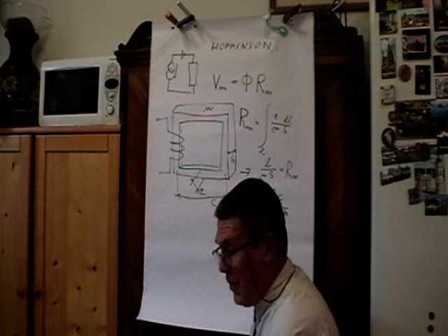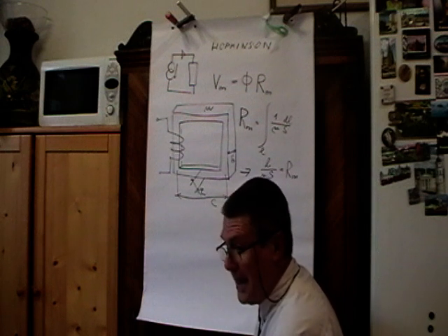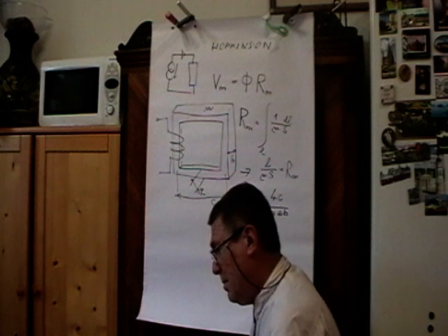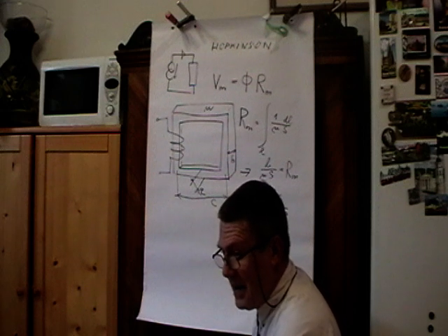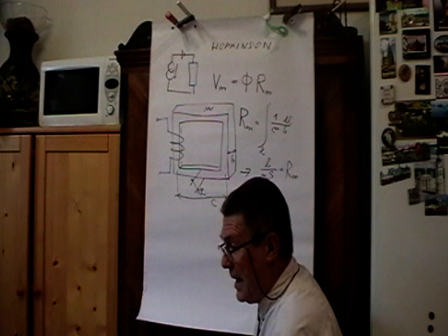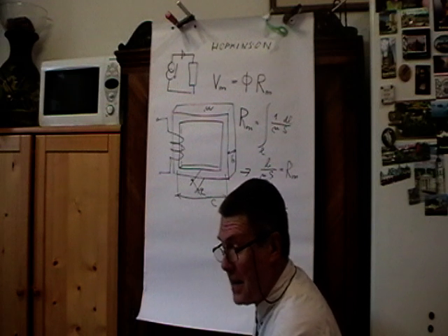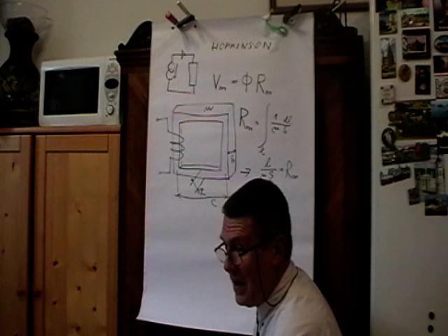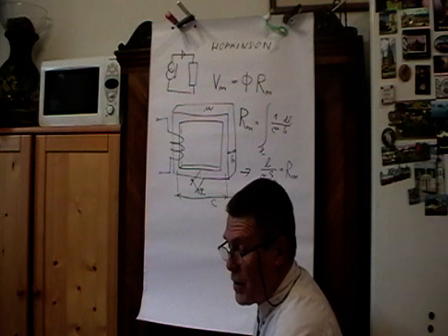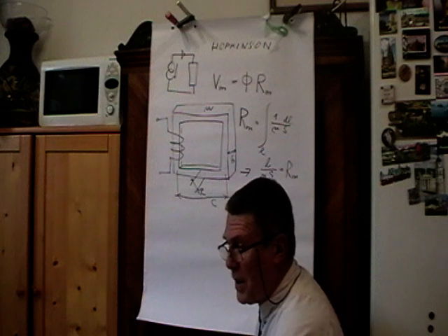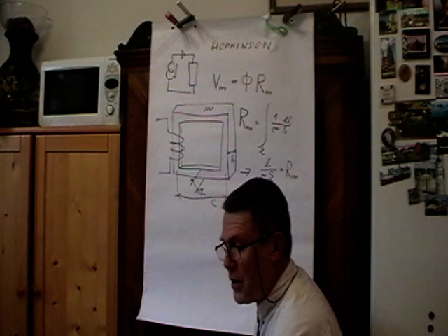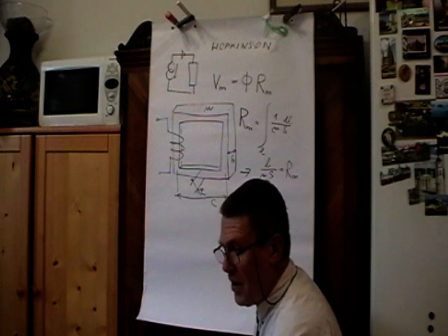And fortunately we have materials like steel with relative permeability, that is, they can guide magnetic field, let's say 1000 times better than the air. Now there are also special materials, mostly called permalloys and supermalloys, which can get 1, 2, or even 3 orders of magnitude higher in special circumstances.